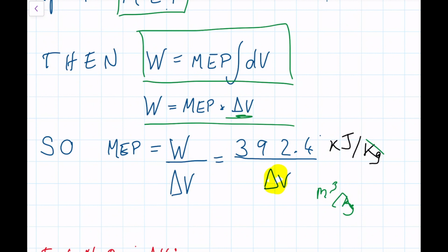So for us to solve this, we're going to have to find the two specific volumes. What two specific volumes? Well, there's only two volumes in this whole problem, right? There's only two volumes throughout the whole cycle: volume 1 and 4, which are the same, and volume 2 and 3, which are the same. So I need to grab these two guys, subtract them to find my delta V throughout the cycle. How are we going to do that? Ideal gas equation.